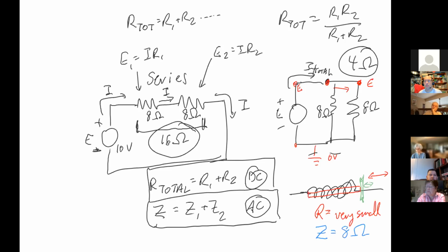And in fact, if you're listening to a speaker right now, which I'm assuming you are, it probably has an impedance of 32 ohms or 16 ohms or something like that. My headphones are probably 32 ohm impedance speakers. That's also why, depending on how you wire things up, if you get current division going through each of two different speakers, you notice that both speakers get quieter than just the one. The reason being that when you get to that node right there, the current has to split. Well, you get, let's say, half of the current.